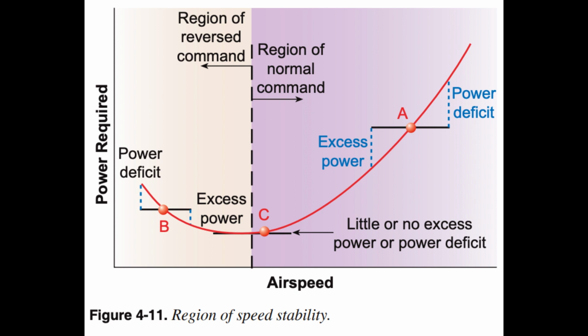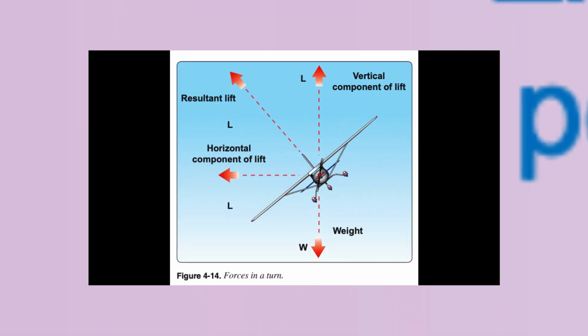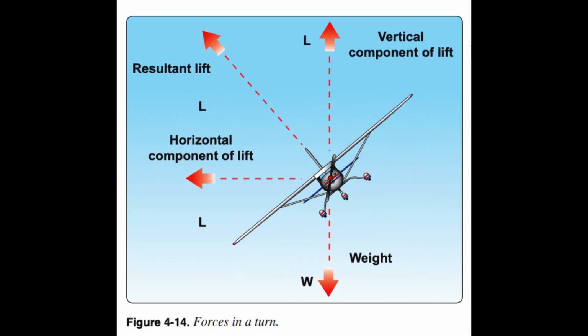Aircraft are usually slowed to a normal landing speed when on the final approach just prior to landing. When slowed to 65 knots, 1.3 VSO, the airplane will be close to point C, figure 4.14. At this point, precise control of the pitch and power becomes more crucial for maintaining the correct speed. Pitch and power coordination is necessary because the speed stability is relatively neutral since the speed tends to remain at the new value and not return to the original setting.